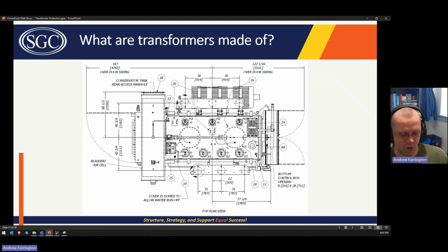So a common issue is when a drafter is drafting a drawing, say with two parallel transformers, and they want to copy one over to another spot instead of, you know, copying it and rotating it and moving it over. They might choose to mirror that transformer, and this happens with breakers a lot too. And if you mirror it, now it's like you've flipped the transformer upside down.